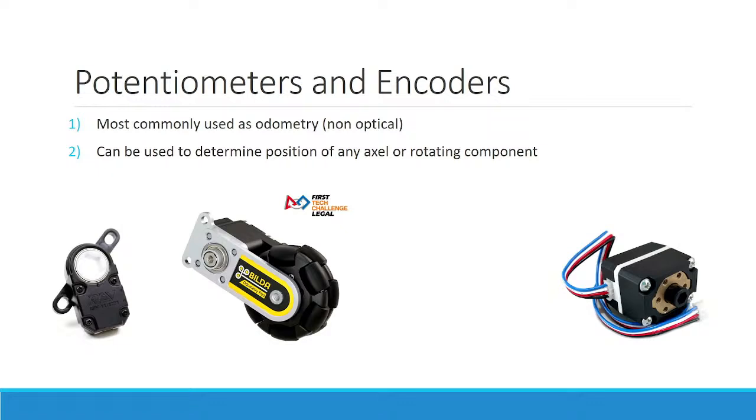Typically, it is something like an omni wheel here that has rollers in the direction it's not oriented, and you line it up perpendicular to one axis, and then you typically have a set of three so that you can tell rotation, you can tell strafing by this one in the back that's facing the other way, and you can tell forward and backward motion. So by having all three, you can tell how your robot has twisted and driven in X and Y axes, and they're using encoders to do that.